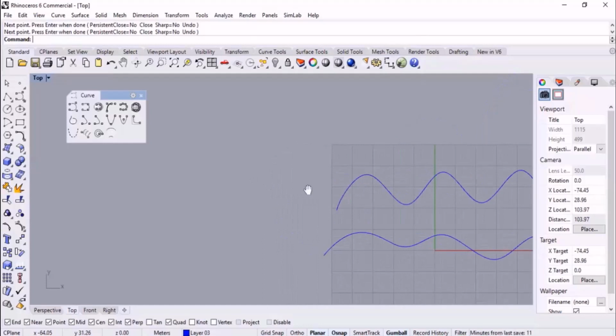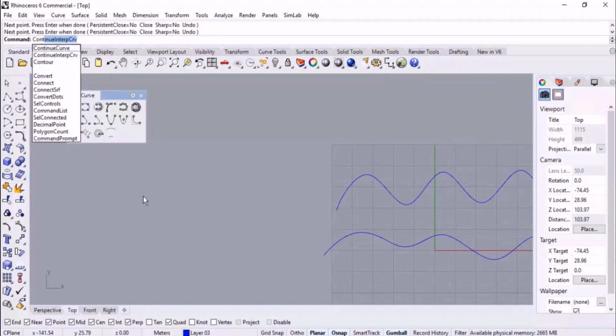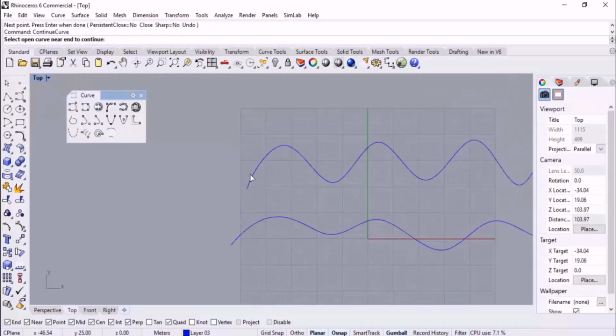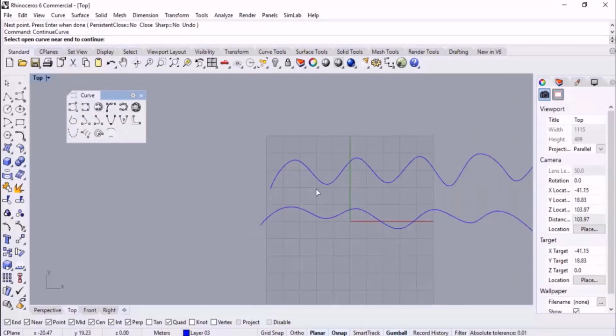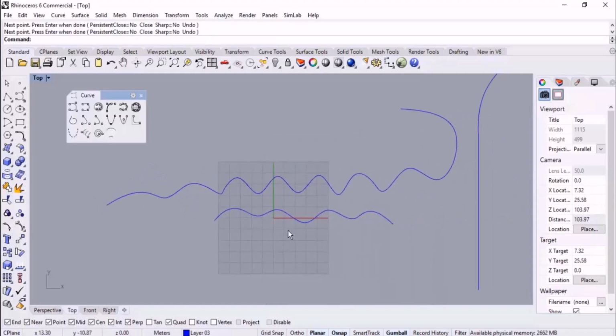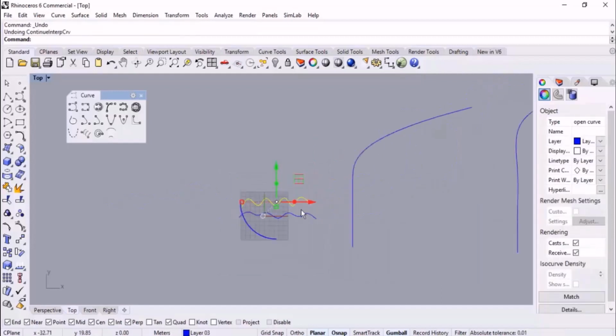But if you wanted to continue them by using control point curve, here it is, control point curve. The points got no interpolation with the line or curved line. You can type continue, continue curve. And it does not matter what you have used before or the last type of curve. You can continue your curve in the manner you want. For example, here we got a mixture of control point and interpolate point. These were the two techniques for continuing your curves.